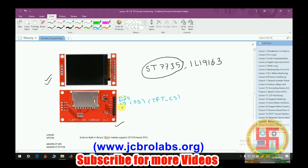Then another pin is reset, which is RST. Then we have another pin, A0. This A0 has different names on different LCDs. In some other LCDs it can be written as D/C, that means data or command register select, or it is also written as DC or RS. All those names represent the same thing.